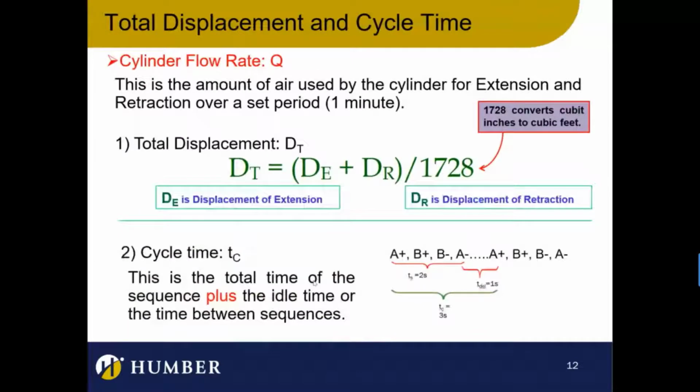That's your cylinder time. Now, we are now experts at understanding how to calculate how much time it takes for some cylinders to do their thing and fully have 1 cycle time and a delay time and then go on. Okay, good. So what's happening here is that when we know that, we have the time it takes for 1 cycle, and we know the actions of the cylinders, and we can calculate the volume that each cylinder displaces during its entire process.